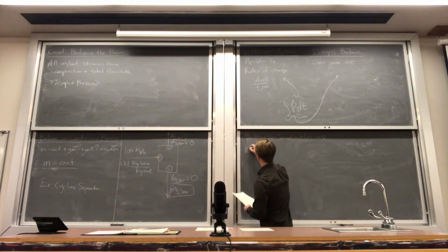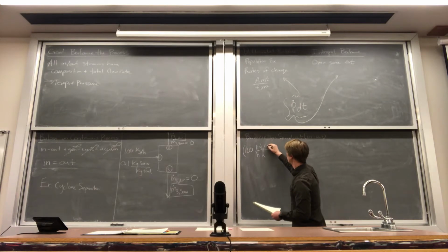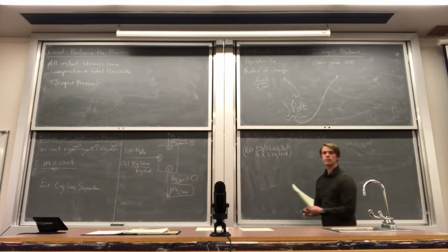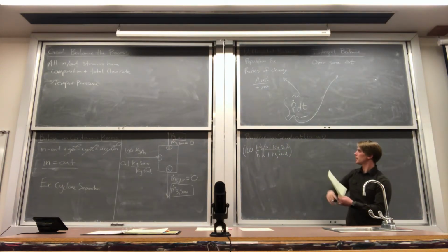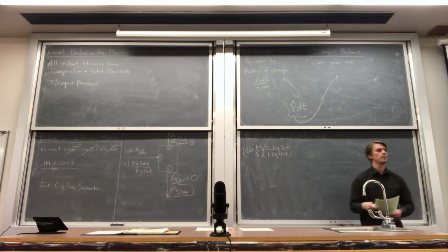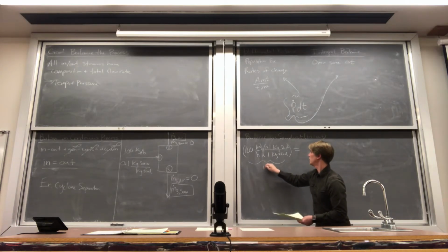So we can write this as 100 kilograms per hour is being fed into the system for every 0.1, you have 0.1 kilograms of the sawdust per 1 kilogram of the feed. Right? So our balance on sawdust, the units have simplified to kilograms of sawdust per hour entry. This is a differential sawdust balance. This is all the material that is coming into the system.